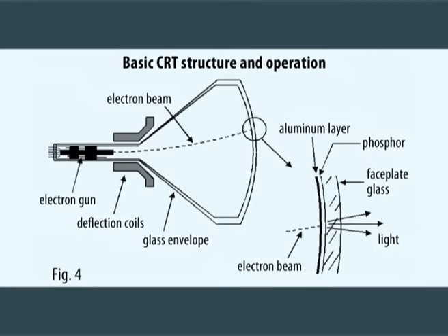Inside a monitor, the cathode ray tube carries an electron gun which emits electrons impinging on inner surface of glass screen coated with phosphor paint. Figure 4 shows basic CRT structure. Whenever the beam is turned on, electrons hit the phosphor and light is emitted. This is white dot. If beam is turned off, no electrons reach coating and the screen remains off or black. The control signal to operate the beam is called as video signal.